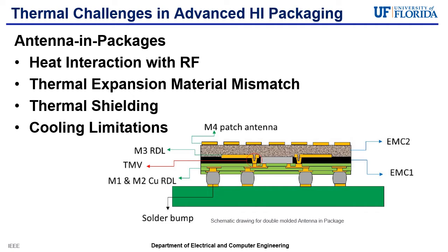Thermal expansion material mismatch is another concern. Different materials in the package expand at different rates when heated, which can lead to physical stress and even failure of the package.